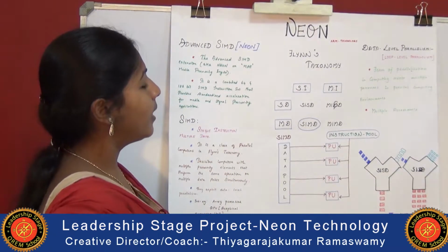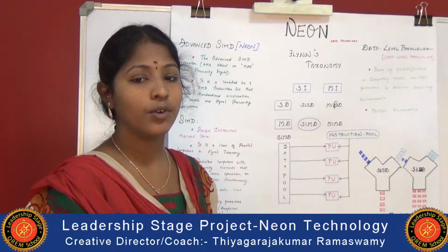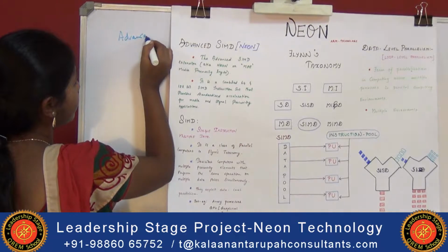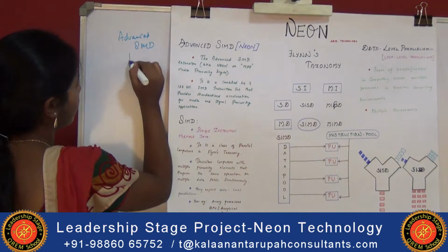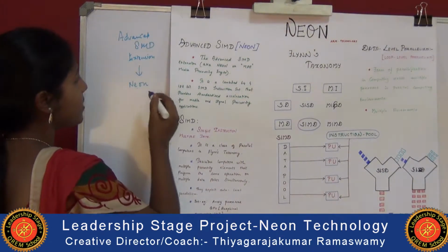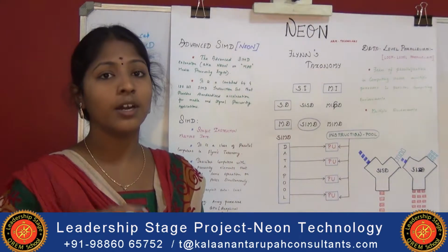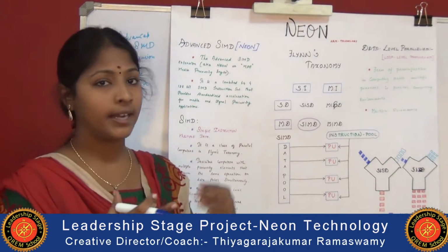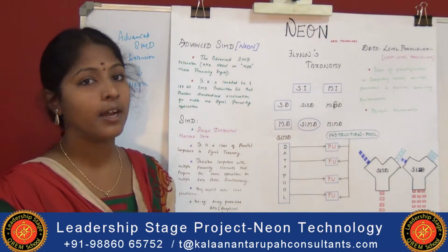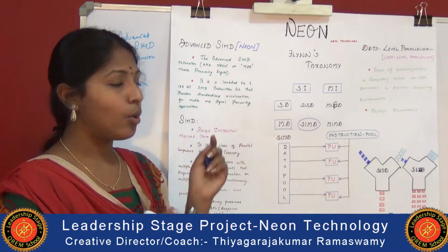That's about SIMD. Now when we come to NEON, what is the background of NEON? This advanced SIMD extension is NEON. The NEON subsystem is nothing but this advanced SIMD extension. NEON also uses a single instruction to perform the same operation on multiple data simultaneously, and it is extremely helpful for media processing, like, as I said, audio and video filters and audio and video codecs.